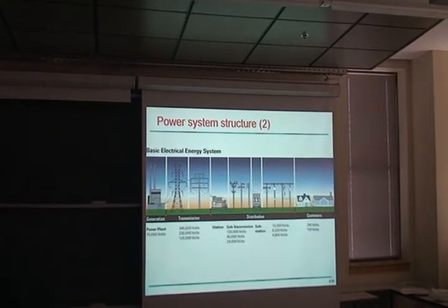Yeah. I got blindsided on vacation once by very high voltage DC transmission. What's the story right there? So if you're transmitting a lot of electrical energy point to point over a long distance, then DC becomes a cheaper option because it only has 2 wires instead of 3 wires. It actually turns out that the resistance is lower in DC than it is in AC as well.